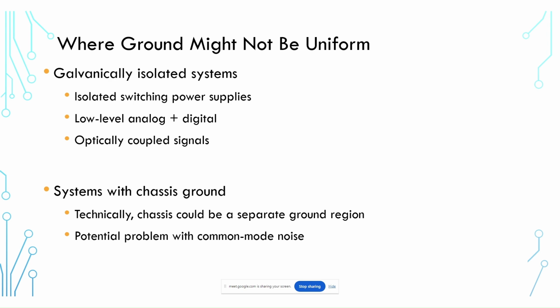Now, common mode noise in a mixed signal system is one reason that we might like to use a differential interface for our analog signals, because, as you should know, differential signals are read by taking the voltage difference between two conductors. And when we take the difference between two conductors, we of course immediately eliminate any common mode noise on that interconnect. So if you do have problems with common mode noise, switching to differential is very useful.